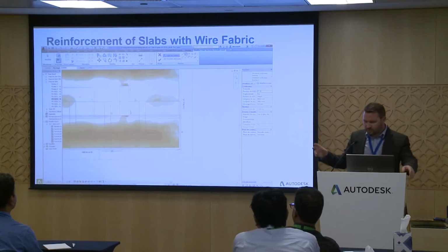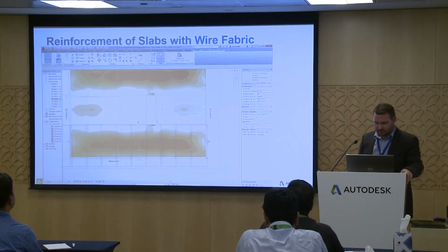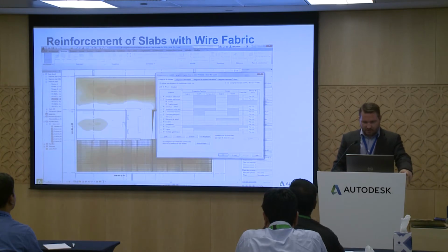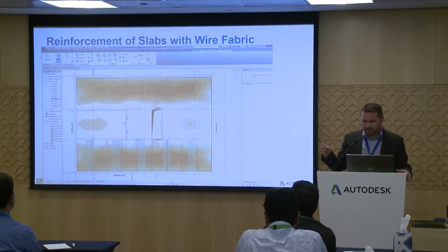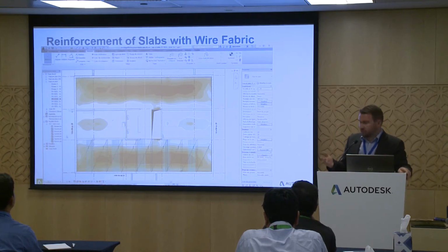After you can choose the way, okay? And once you validate, of course, it will be cut due to the selection. You can choose if it's up, down, and after you validate. And after you can display all rebar for wire fabric, which is not my case, I don't like this. So you can display a more symbolic rebar and with a classic tag convention.